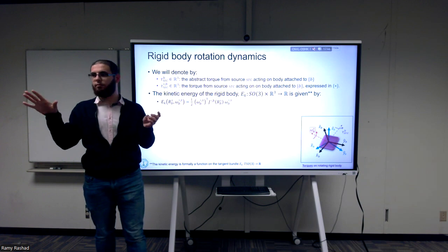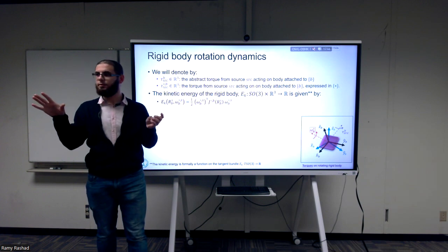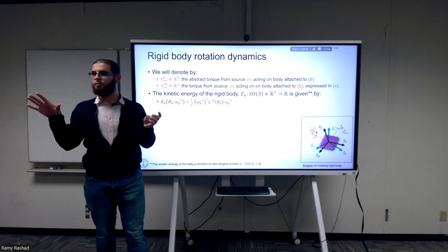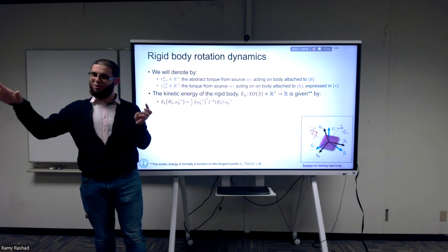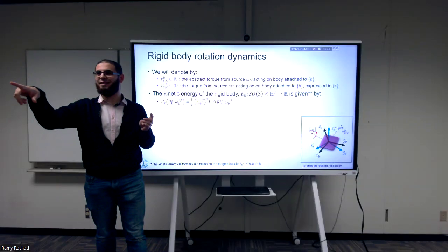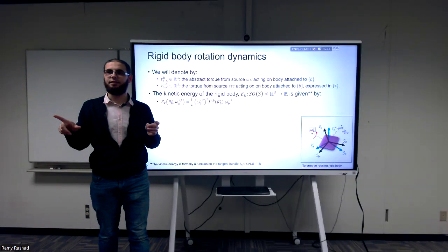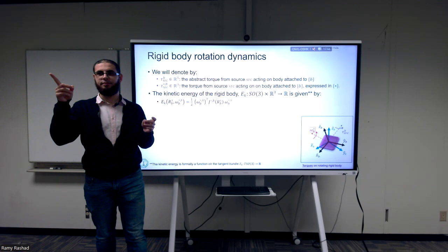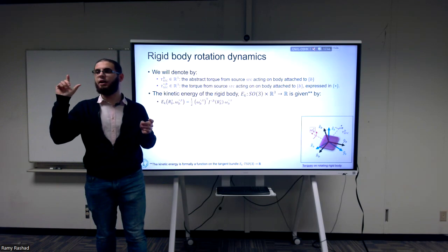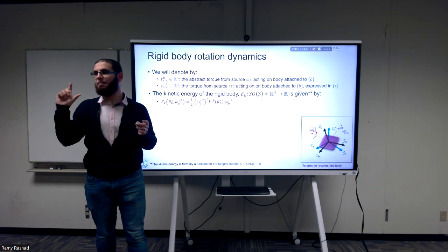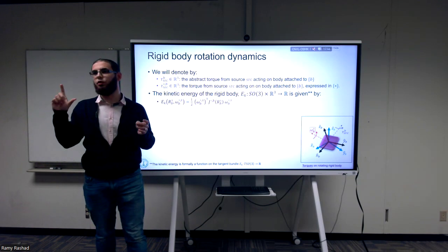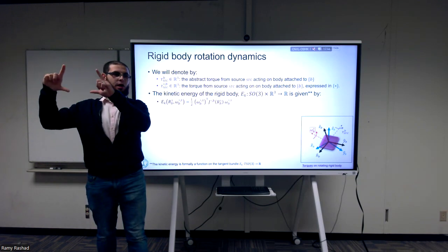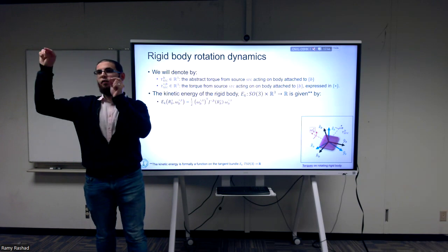Cross product, okay. And can someone beat that? Yeah. The center of the mass. 3. That's wrong. How many numbers do we have? The inertia matrix is symmetric. It's a symmetric 3 by 3 matrix in general, which means that instead of having 9 numbers, I have only 6 of them. The 3 on the diagonal and the off diagonal ones.